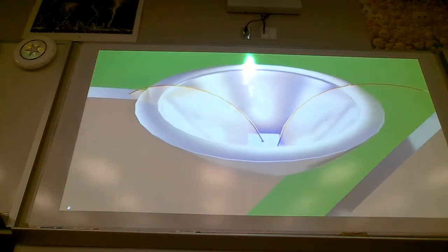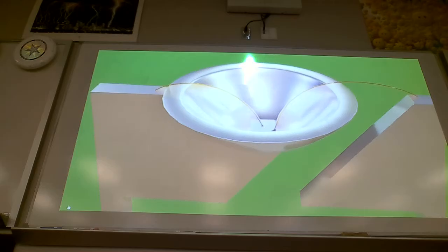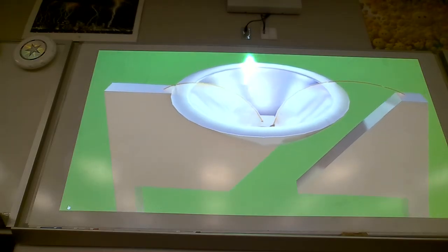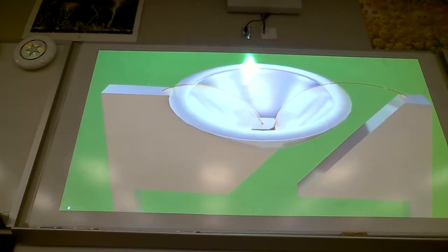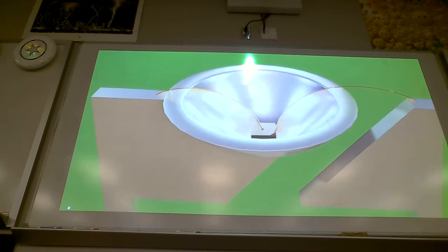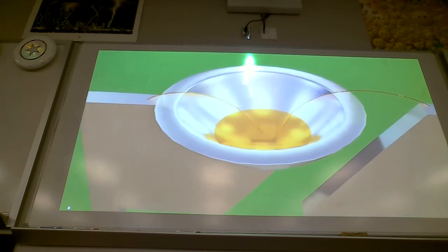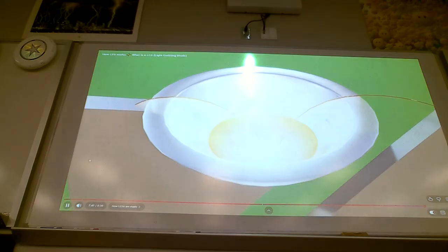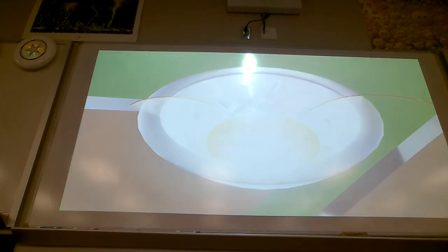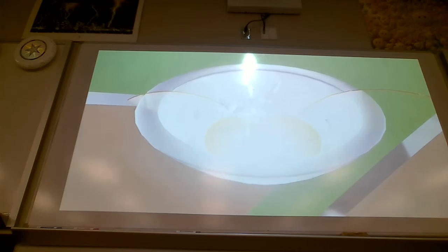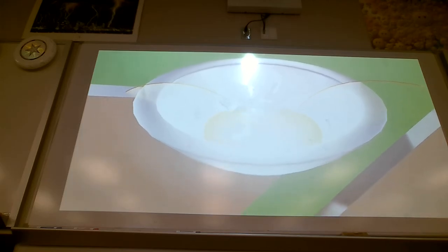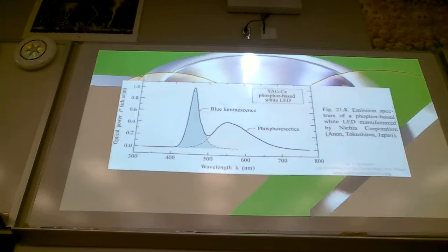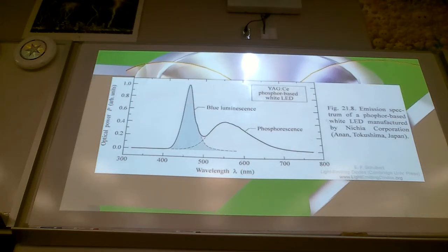But to be more efficient, we will add a small reflector to direct the light, which will be integrated in one of the electrodes. And before covering everything in a transparent epoxy resin, so that the set is more resistant, we will add one last element, a layer of phosphorus, although this is used only in some cases such as white light. In this particular case, the diode is actually emitting a blue light, which upon impact on the phosphorus layer, causes this to emit a more yellow light. The mixture of these two spectra is what generates the perception of seeing a white light.